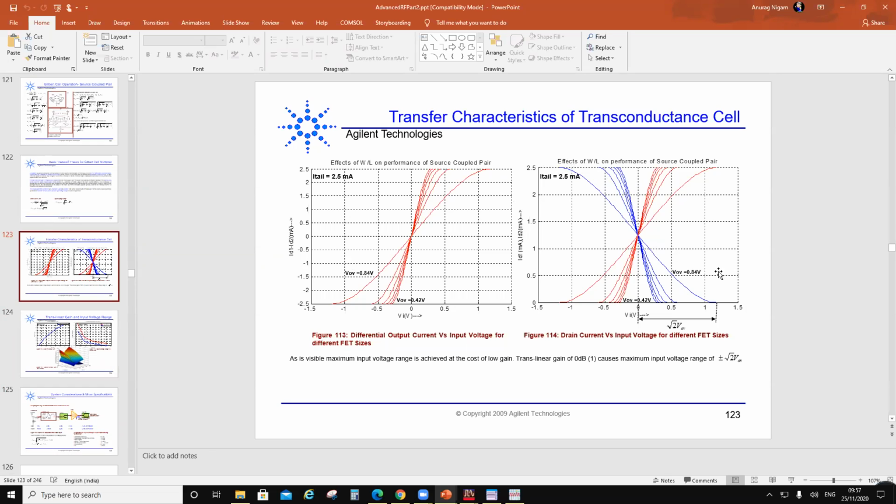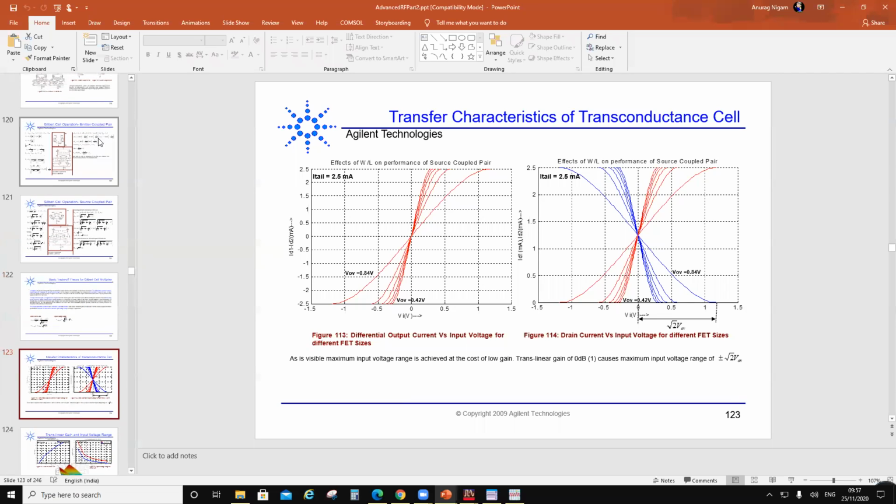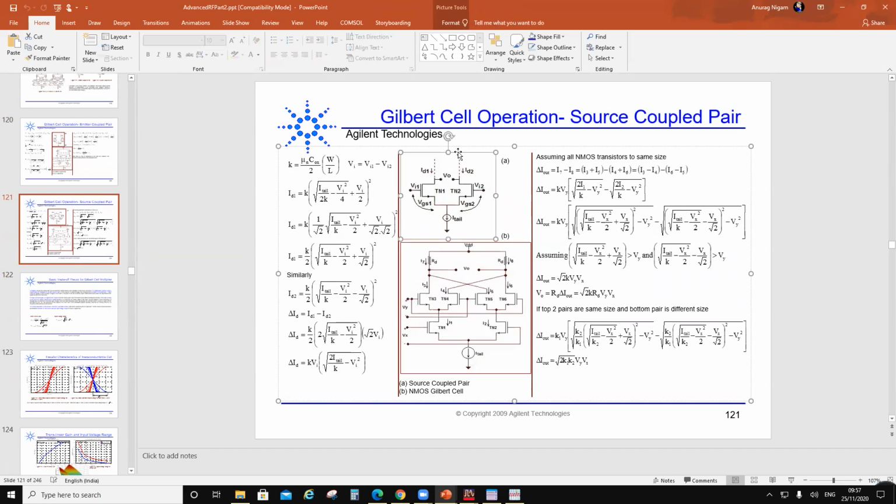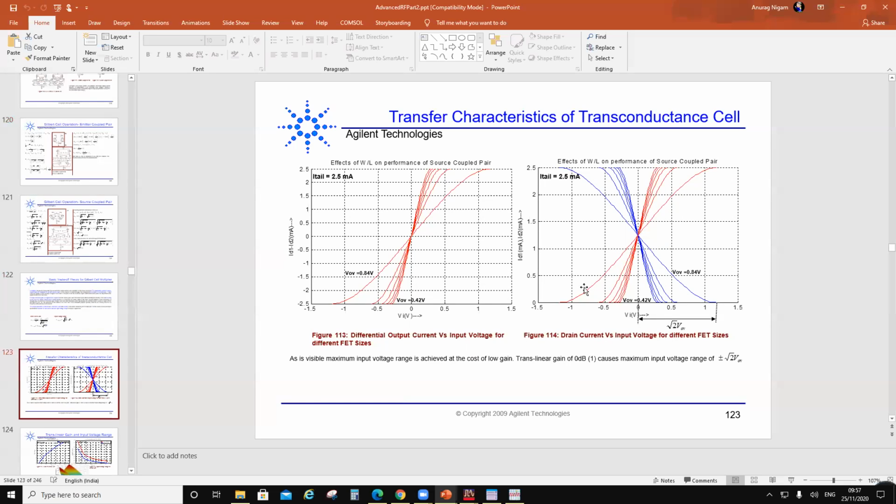The current is going to steer in a translinear cell. So let's pick any translinear cell. This is a translinear cell. What is going to happen is if I change Vi1 minus Vi2, that's a differential input, then I'm steering ID1 and ID2. If I plot ID1 and ID2, one of the currents is going to drop, the other current is going to increase, because the summation is going to be the total tail current.